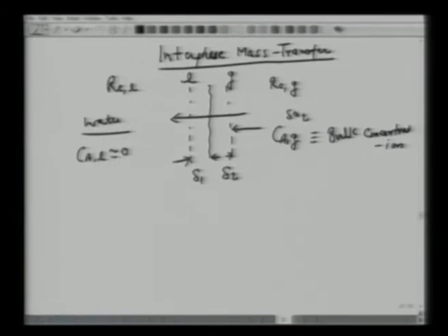So when we say interface mass transfer diffusion, all we are trying to say is that now the concentration will drop from here, from C_AG to an interface concentration, which we can say is C_Ai. So concentration now drops from C_AG to C_Ai, or for the gas phase we can say that it drops from y_AG to y_Ai. So now the concentration drops at the interface.